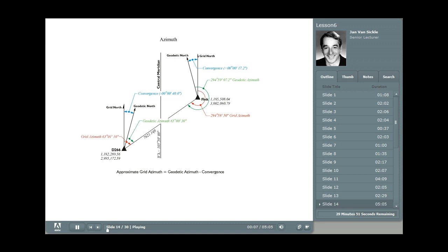Okay. Now that we've talked a little bit about the reduction of a distance measured on the Earth's surface, and there's more information on this, of course, in your reading in basic GIS coordinates, let's just spend a second looking at directions in state plane coordinates. Now, you will find that every zone in a state plane coordinate system has a central meridian. In Colorado, the central meridian is 105 degrees 30 minutes west longitude, as shown here on this slide.